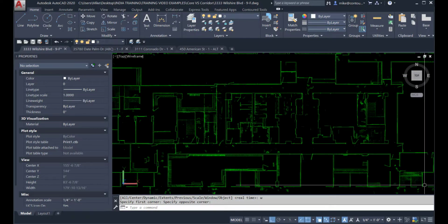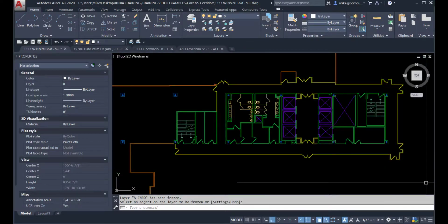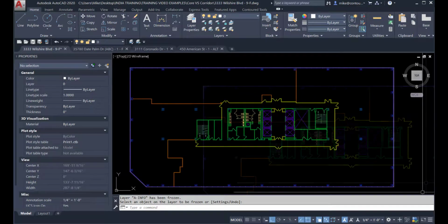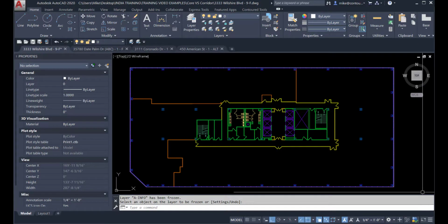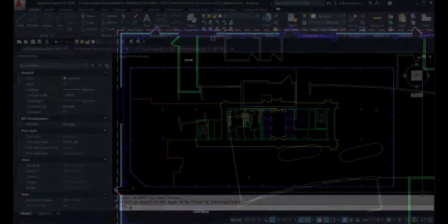This corridor is quite straightforward and simple to determine. It wraps all the way around the core rooms in the center of the building. It extends to all service rooms and all tenant spaces. It provides access to all necessary parts of the building. Anything that lies outside the corridor is tenant space. A building engineer will not have to go through tenant space to access any service room in this example.